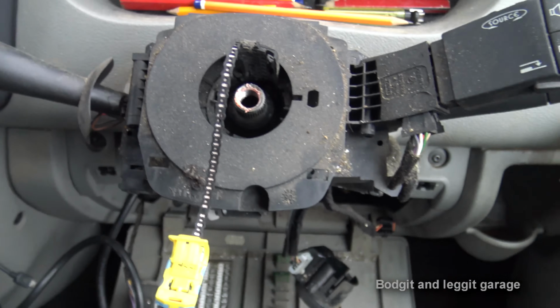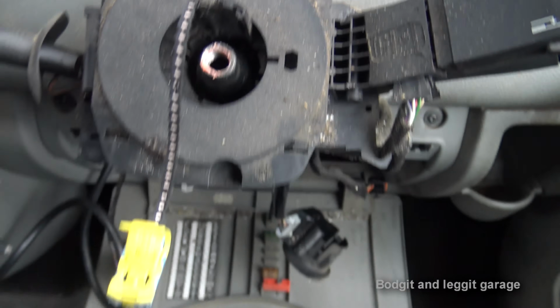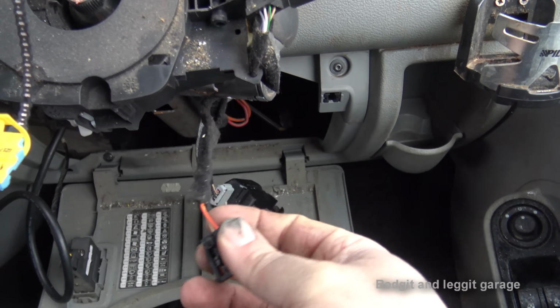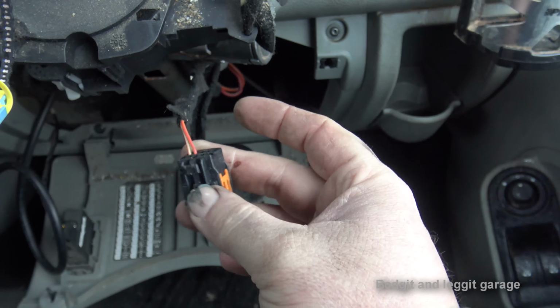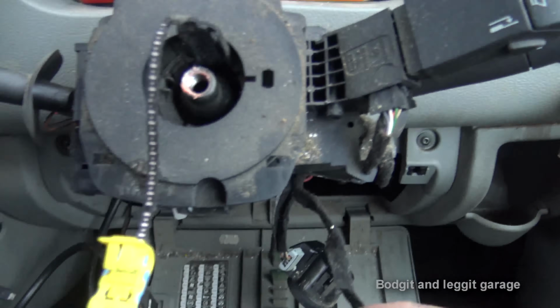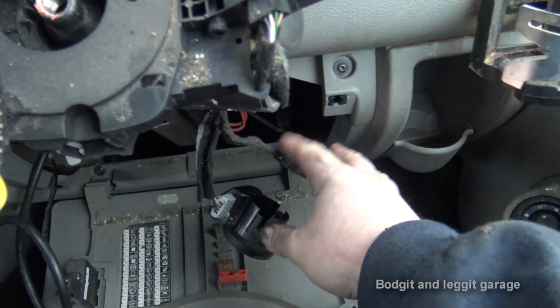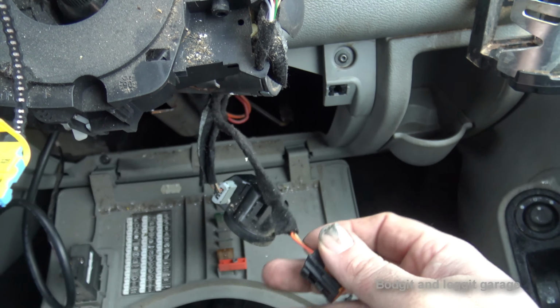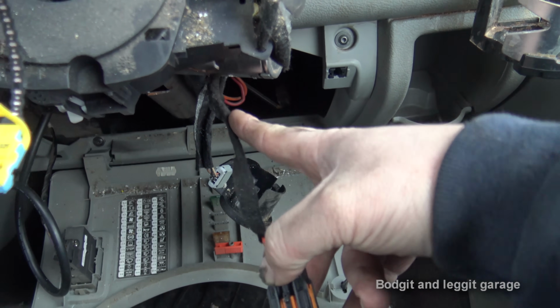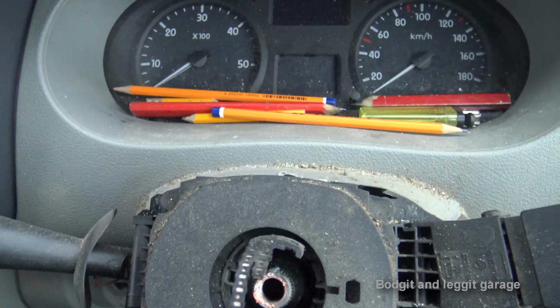Right, I've gone down a slightly different route because I didn't want to take all that off if I didn't have to, but it is kind of looking like the clock spring. I've disconnected the wire at the back, which goes into the clock spring. So I'm going to do the same thing again with this and put my resistor into this. If the light then goes off and stays off, then we know we've got a problem in the clock spring, and we know that the wiring from here all the way down is okay. Now if it doesn't go off, we then know we're going to have to trace a wire. It could be a module, it could be a broken wire, it could be loads of things. But these are the simple tests to do first.